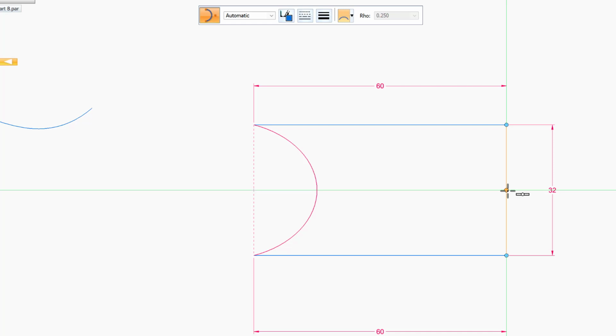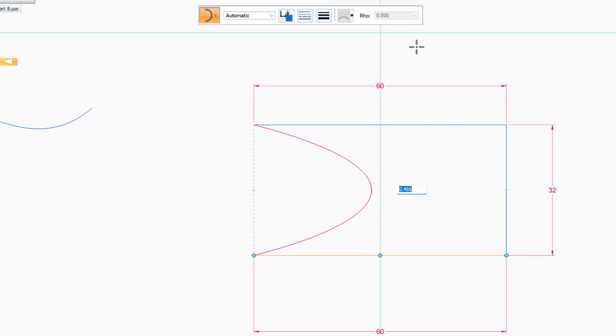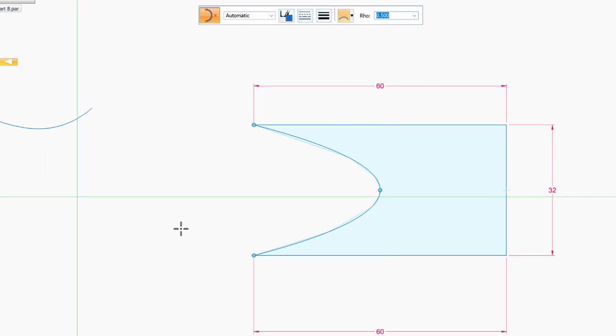But did you notice something here? It tells you this value here, and the value is 0.5. 0.5 of what? Of the dimensions here. So if you want to make it 0.5 of the dimension, let me make it 0.5. Enter. It means that this ellipse has its axis from the tip here to this one here.